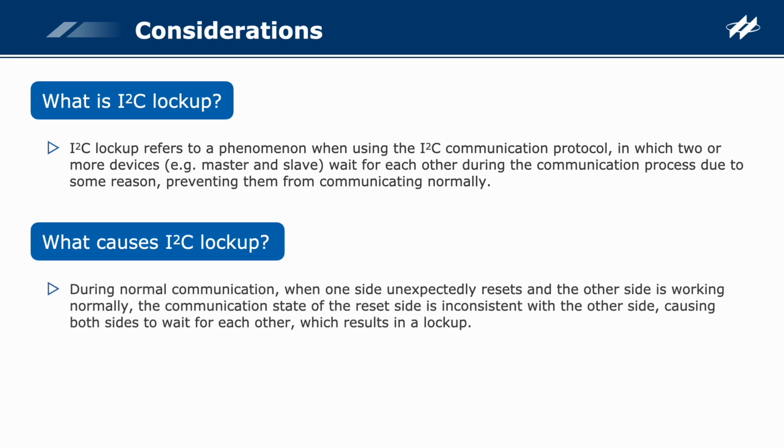During the normal communication process, one side accidentally resets while the other side is working normally. The communication state of the reset side is inconsistent with the other side, causing both sides to wait for each other, which results in a lockup.